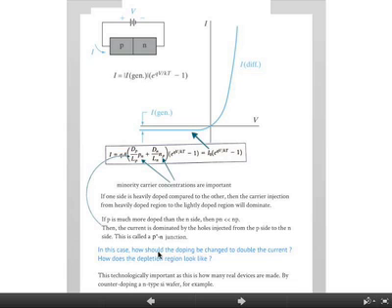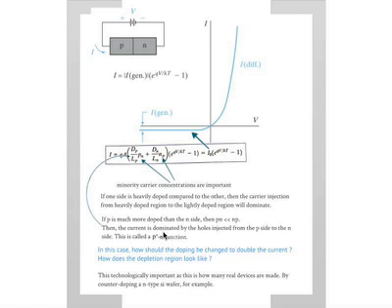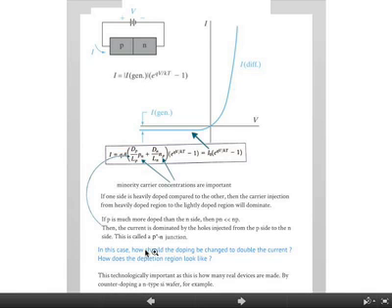Of course, when you have a highly doped P side, the depletion region on that side is very small too, and that turns out to be a key reason why that needs to be heavily doped. Remember, the extent of the depletion region depends on how heavily doped these are. If it's very heavily doped, this region goes smaller, because there are few charges needed, since the concentration of charges is so high.